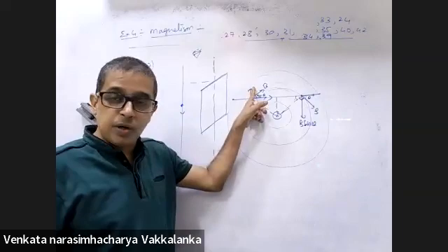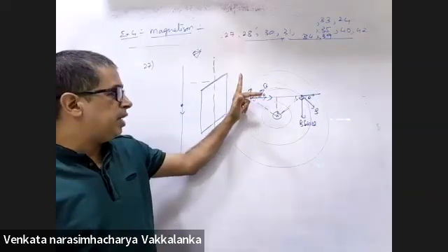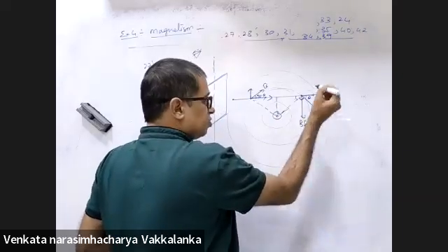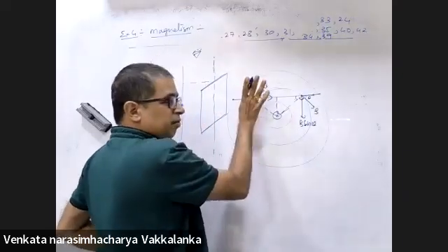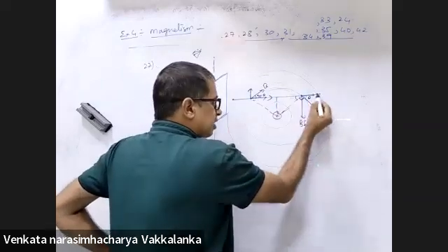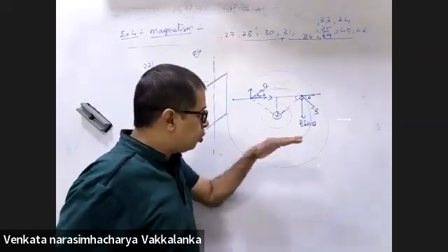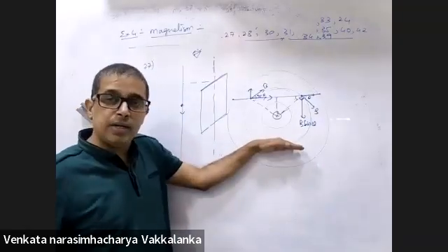Vertical component will produce a force. F = BIL. Force will be outwards. That means the right segment, force is inwards. Left segment, force is outwards. Can you calculate the torque on that element? Yes, sir. Do the same thing for the lower element.